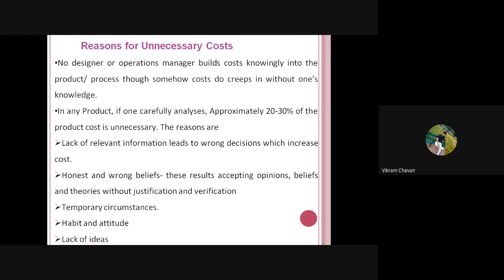But that concept, if any worker doesn't know it, then the consequences will happen. Before machining, if that worker performs the heat treatment and then transfers it to machining, there will be more tool wear for that particular product. And more time is required to perform the machining, so the effective production time will be lost, and the products produced have certain problems, certain stresses. Okay, so those are the consequences.